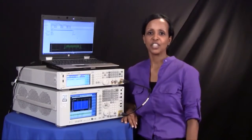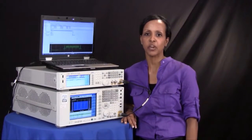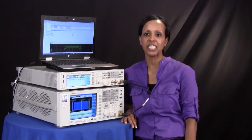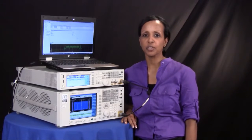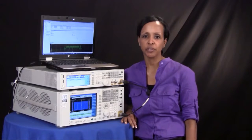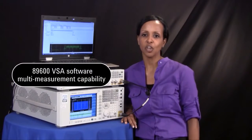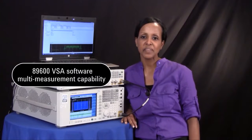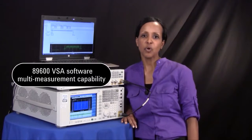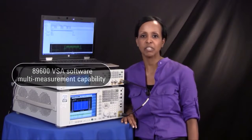The third challenge is mostly for R&D engineers who are interested in testing beyond what's defined in 3GPP Release 9 and also need tools for troubleshooting, for example, if the multiple MSR signals interact with each other. Agilent addresses this challenge with the 89600 VSA software multi-measurement capability. It's the ability to process multiple measurements for multiple signal types all at the same time.